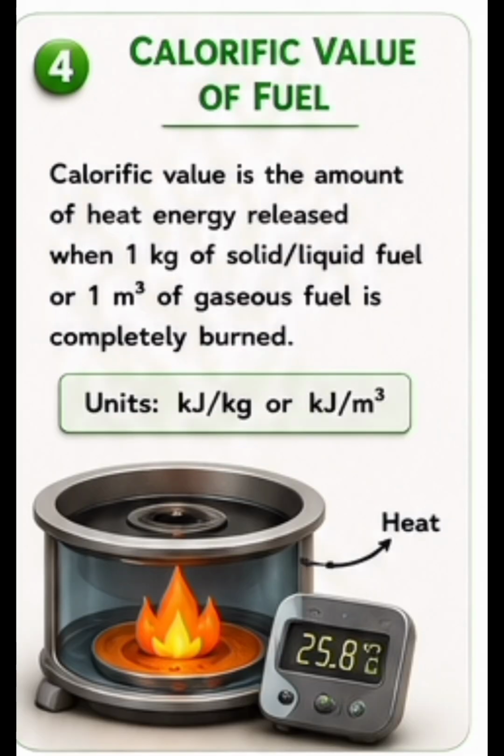Now let us understand the calorific value of fuel. Calorific value is the amount of heat energy released when 1 kilogram of solid or liquid fuel, or 1 cubic meter of gaseous fuel, is completely burned. It is expressed in kilojoules per kilogram or kilojoules per cubic meter.